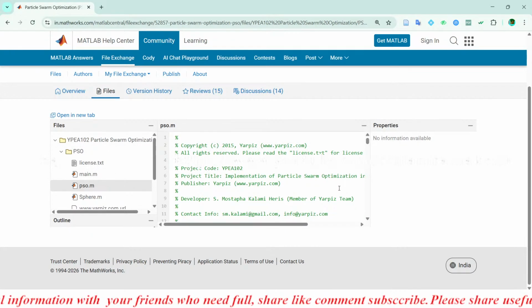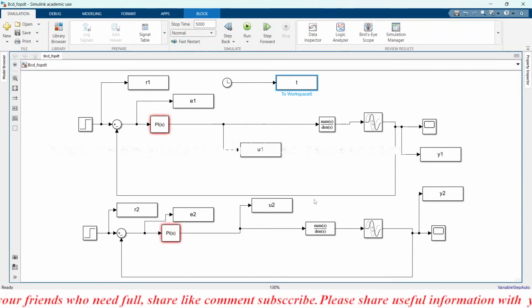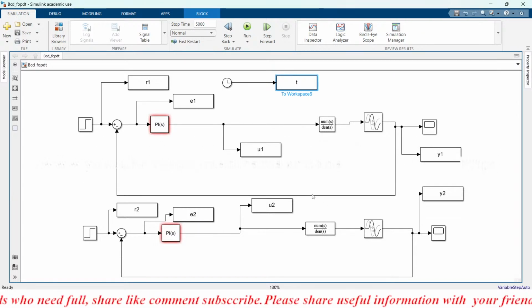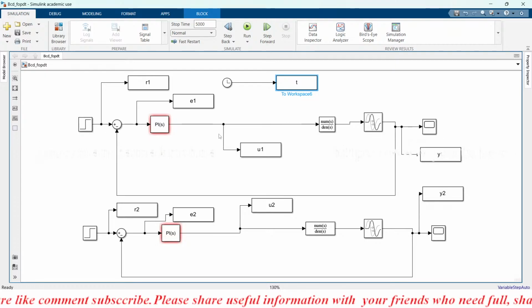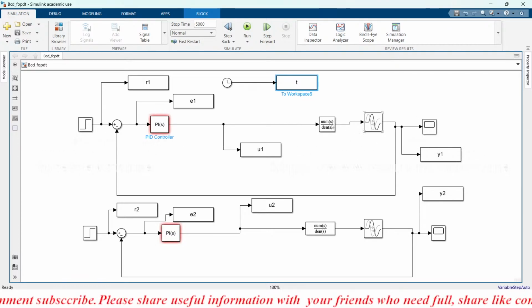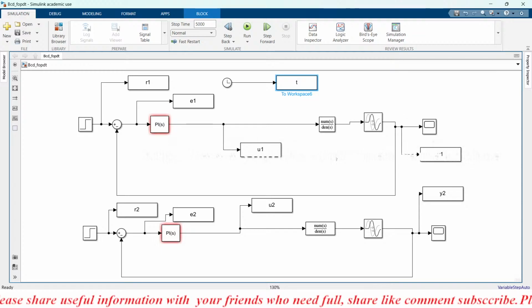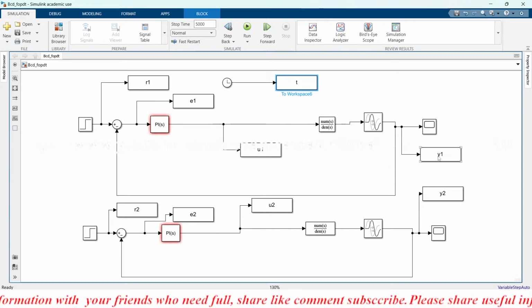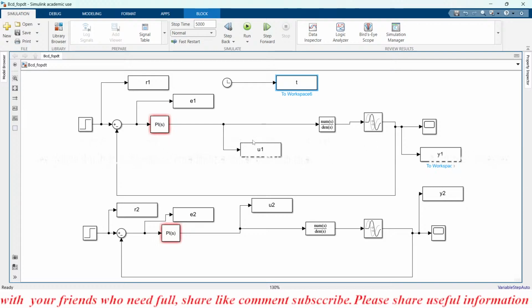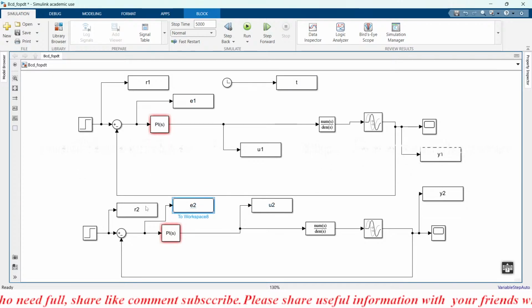Now we will see the code. Okay, so this is our code. What we require for optimization is a step response, the PI block, and the transfer function. I have taken the FOPDT, first order plus dead time model. Here I have the input signal and output signal. This is our control signal always, and here is our error signal.